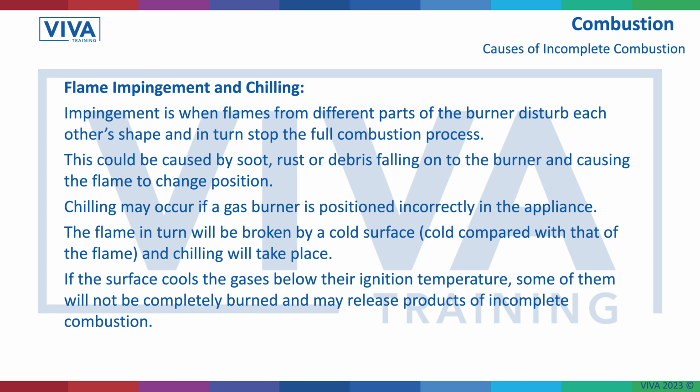Now, if the burners are correct, the flames are coming up, but if they're not put in properly, the flames can touch each other and impinge, and then when they're touching, you get a cold spot, and that can cause sooting. Carbon is, if you compressed it for long enough and hard enough, you get a diamond. We can't do it for that long, but what happens is the black sooty remnants are left. As the flames are touching, we're getting incomplete combustion, and one of the products of that is this black sooty carbon, the soot that formed on old coal fires and things like that.